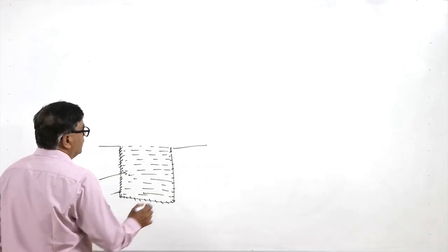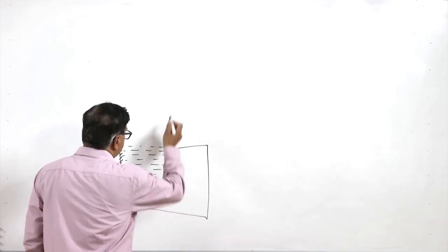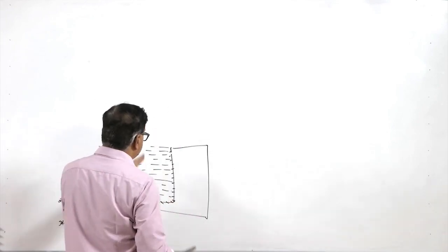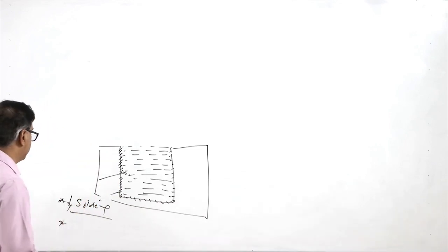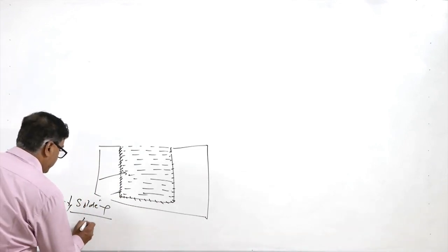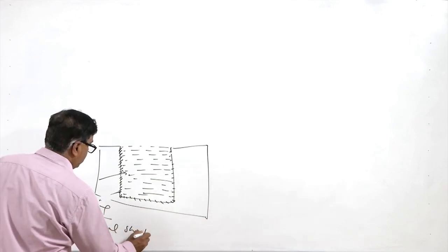So, soldering needs to be reduced. And another thing, the metallic mold, when poured with the molten metal, suddenly experiences a lot of heat and the high temperature of the molten metal. So, it will have to deal with the possibility of thermal shock.